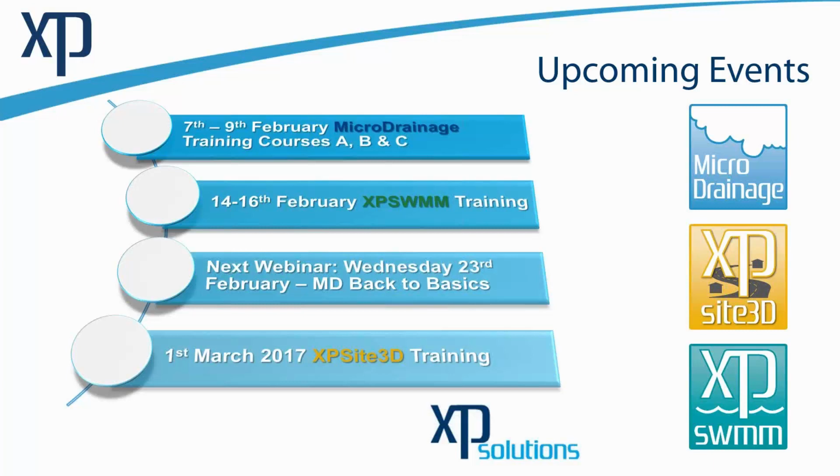Sorry, Peter. Very good question. Which LiDAR would be best suited for this, DTM or DSM? On one hand, many may think the digital surface model, DSM, is good for such purposes because you don't need to digitize the houses. But if you are using a DSM, be careful, because if your property is obviously identified on your LiDAR, there is no chance you can make water flow inside it.